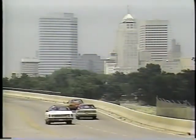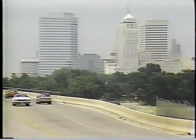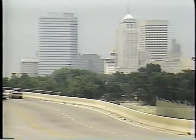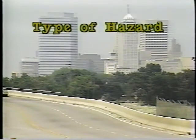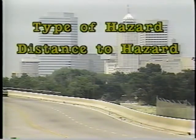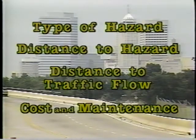Traffic barrier selection, meaning the choosing of one particular system to meet a specific safety need at a certain location, depends on 4 things. 1, the type of hazard requiring a barrier. 2, the distance from the barrier to the hazard. 3, the distance from the barrier to the flow of traffic. And 4, the cost and required maintenance of the system.